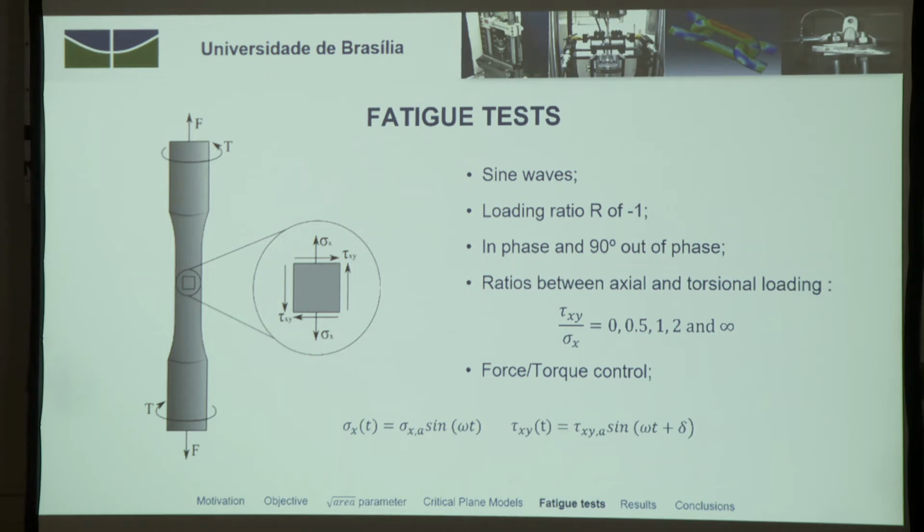All the fatigue tests were performed with sine waves and a loading ratio of -1. We conducted tests in phase and 90 degrees out of phase, with loading ratios of 0, 0.5, 1, 2, and infinite. That means pure torsion and uniaxial loads too. Our tests were conducted in force control with sine waves.